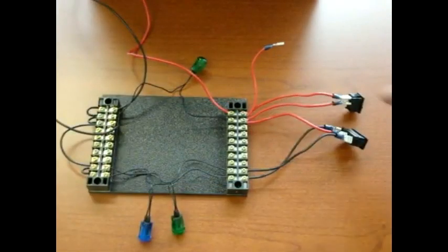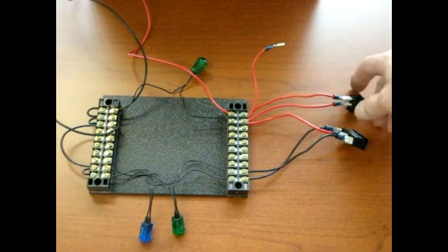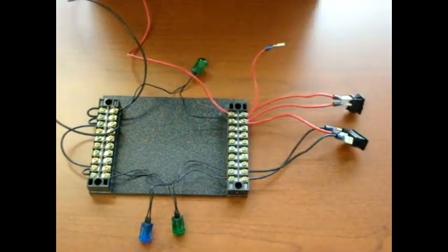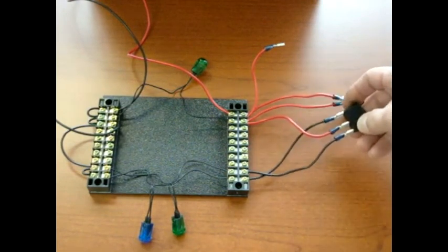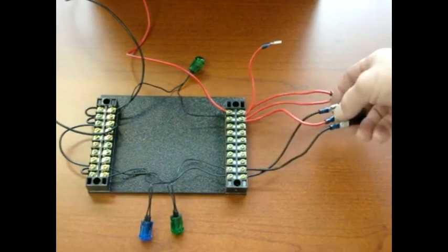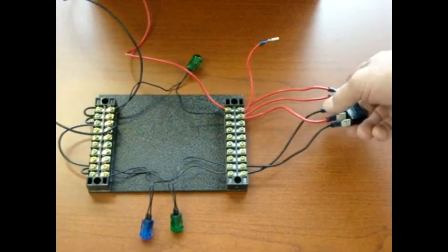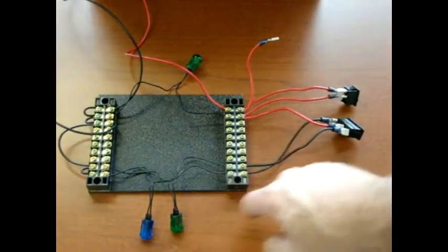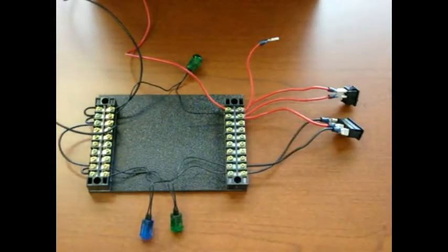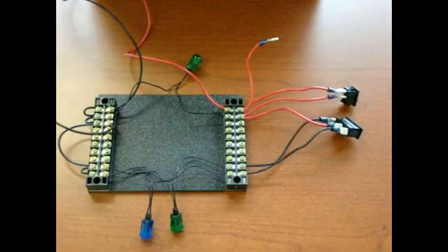Okay, I still have our single pole single throw switch set up. So when I switch it on, our green indicator light will come on up there. It's also going to provide power for our single pole double throw switch here. The red lead being our positive, going to our common. And then one position will go to a green light, and the other position will go to a blue light. So depending on what position I have this switch in, either the blue or green light will be on.